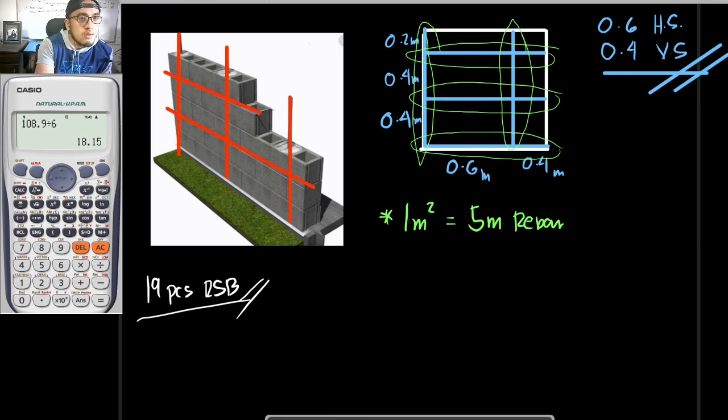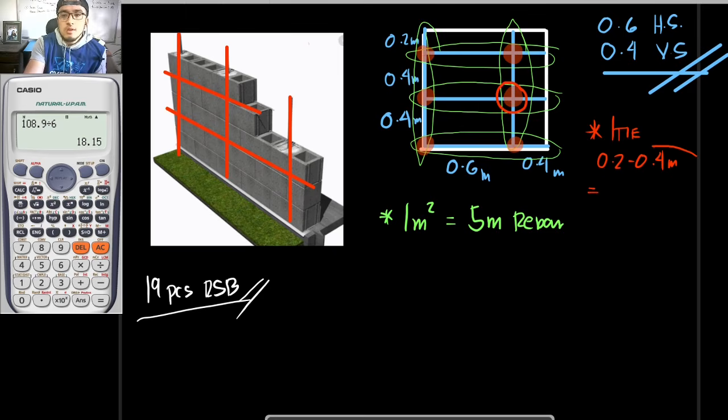So, ito, maglagay tayo ng red marks. In these joints right here, you would be tying them, yung mga alambre, GI wire. And in one tie, note, one tie is approximately 0.2 to 0.4 meters. Ganun kahaba yung alambre na kailangan natin kada isang tie. And in our estimation purposes, since it would range from 0.2 to 0.4, let us use 0.3 meters per tie.